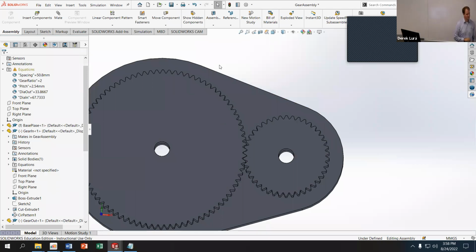All right, so like we talked about before, these trapezoidal gears, the flat face gears, are not going to be efficient in transmitting torque because of the movement of the contact angle and the contact location in a sporadic way. So if we use an involute gear, we should be able to get a much more consistent pressure angle. And so our torque transmission will be nearly constant, which is much better than having vibrations inside the system, especially if you're trying to transmit high power. If you're doing really low power systems, it doesn't really matter that much, especially if they're moving slow.